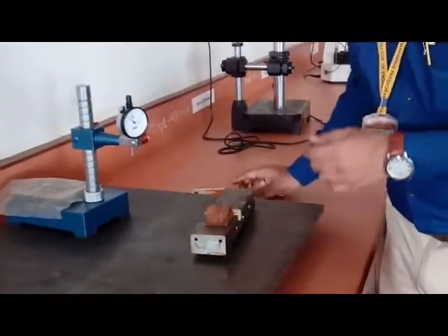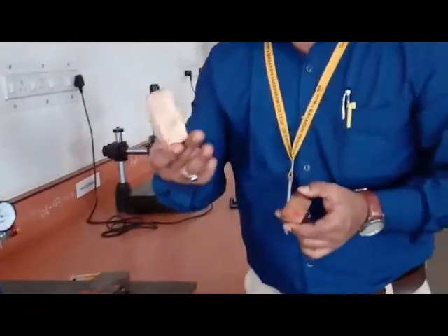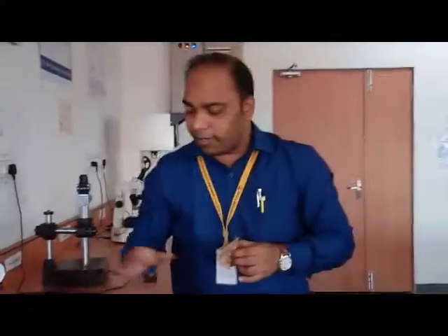And using this technique of experiment calculation, we can find unknown angles of any component using the sine bar. The only condition is that this is not the correct or accurate method, but this is the precise method or precision method which is used widely in the industry to find angles of different unknown components. If the component is of larger size, then in all those cases, this sine bar is directly kept onto the workpiece, and the calculations are made. The only thing is that an external plate is not required.